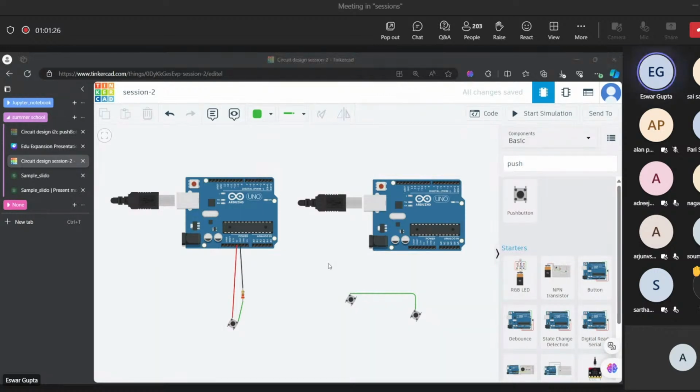I hope everyone got the connections up to here, as I had waited so much time up to now. So I'm moving on with the next connections. What you need to do next is, there is this pin, terminal 1B. Connect this to either A0 or A1 only, not any pin. A4 and A5 are reserved, and I will say why they are reserved. So connect to A0 now. This pin 1B to A0.